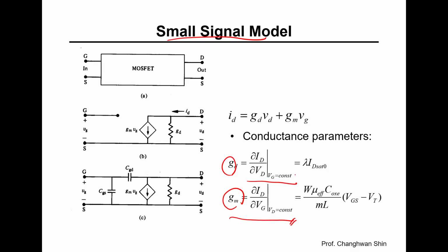The transconductance GM quantifies how effectively the gate voltage controls the drain current, as described in this differential term. Higher GM means better voltage gain capability, which is like how a sensitive steering wheel provides better control over a vehicle's direction.